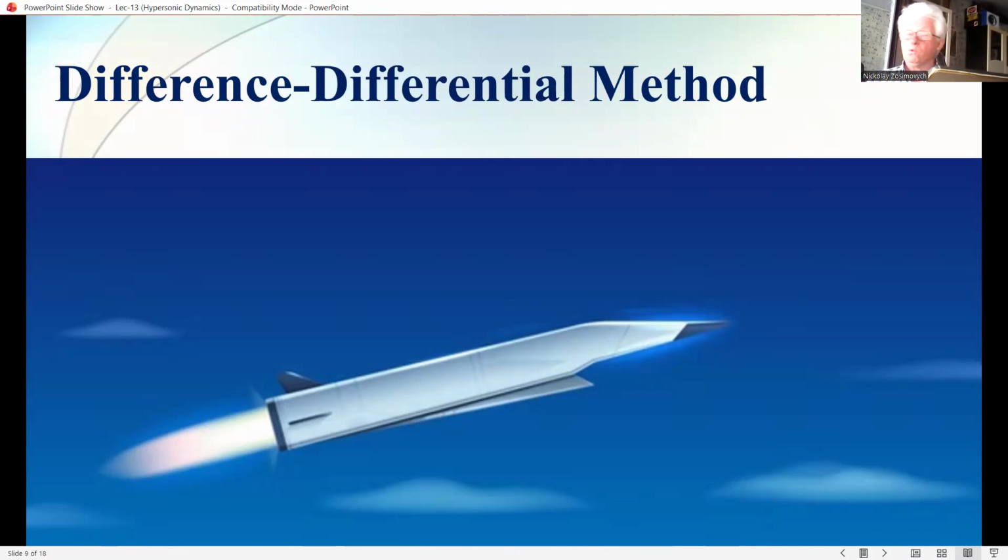Our next topic in today's lecture: the differential method. Unlike the approximate local similarity method just discussed, the differential method is inherently an exact solution of the general boundary layer equations. The general idea was originated in 1937 by Hartree and Womersley, but was not applied in a practical sense until the work of Smith in 1960. Smith utilized the differential method extensively, and the idea is as follows.